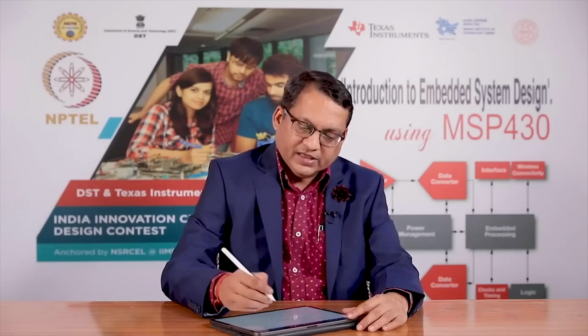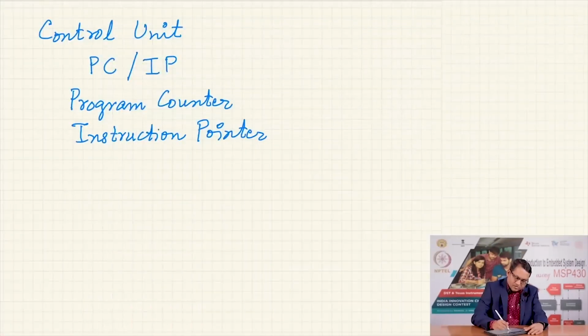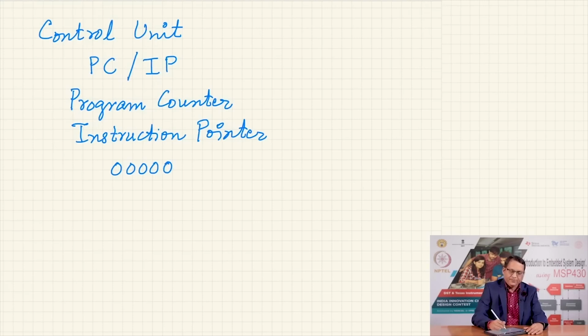All microcontrollers require that after reset, a fixed location, a known location is accessed to access the first instruction stored in the memory. In many cases, that address is 0000, say, or another 0 if you like, this address. So, this address must be output on the address lines connected to the program memory. If you do not reset,